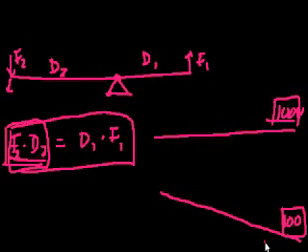That's 100 newtons. And let's say I know that the maximum downward force that I am capable of applying is only 10 newtons, right? So I want my force to be multiplied by 10 to lift this force. So let's figure out what would happen. My input force is 10, and I want to figure out the distance to the fulcrum. So let's say my input force is 10, and let's call this the input distance. And I want the output force to be 100, right?